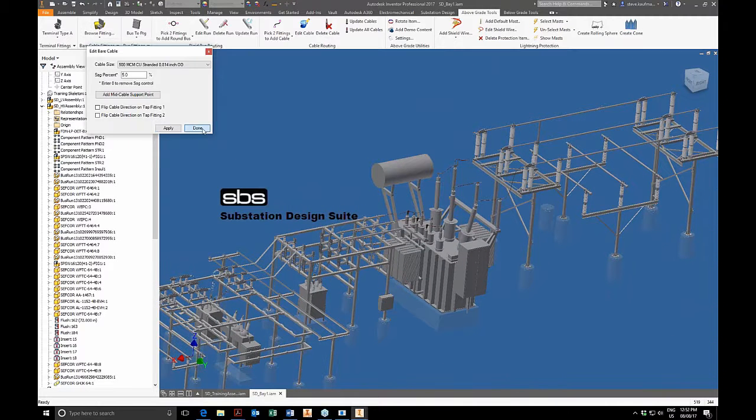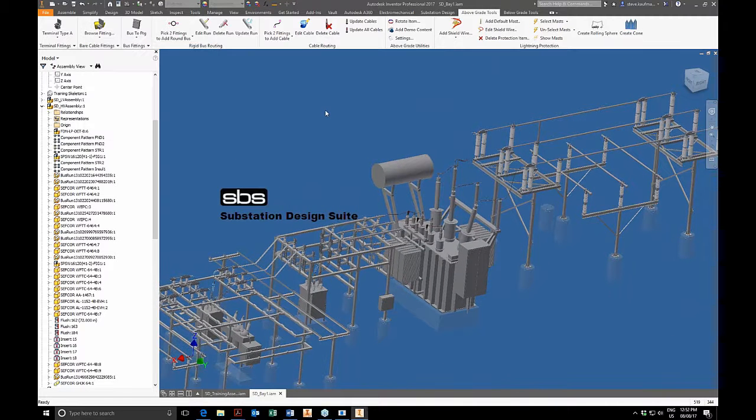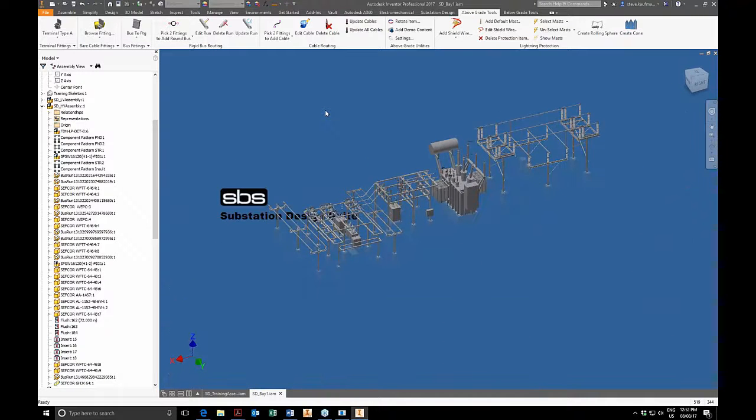So yes, if you change the height, it updates. What a lot of people do is template maybe this whole assembly, have it fully populated, and save it somewhere. And if they have a new job, they copy that template out, place it in their location, adjust the heights, and tweak it to whatever that location needs, and then they run it from there. So that's a typical workflow for that. Nice question, Wayne.